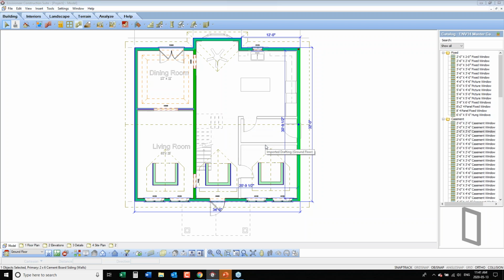Or you could just start over to make sure that you've got it in at the right scale. That's why we bring in that PDF file there, when you have it in that dialog box, to check that scale. Most important thing to do. But not all's lost. You can click on all these walls and change them if you need to, if you've noticed too late that you've brought it in at the wrong scale. Next question.